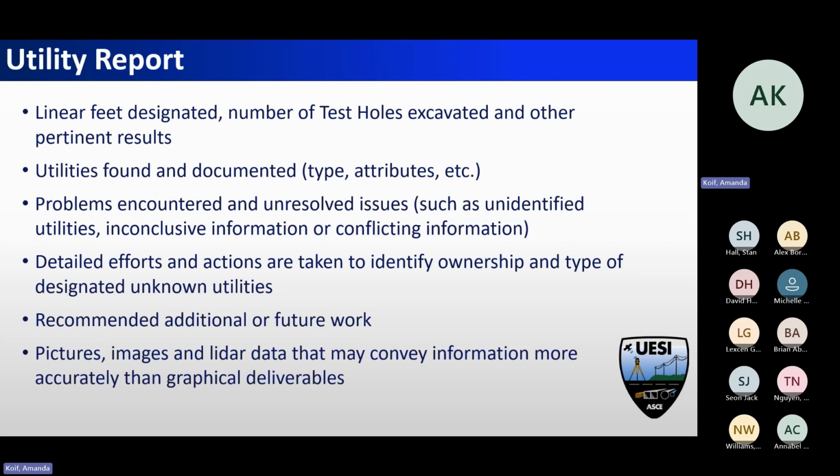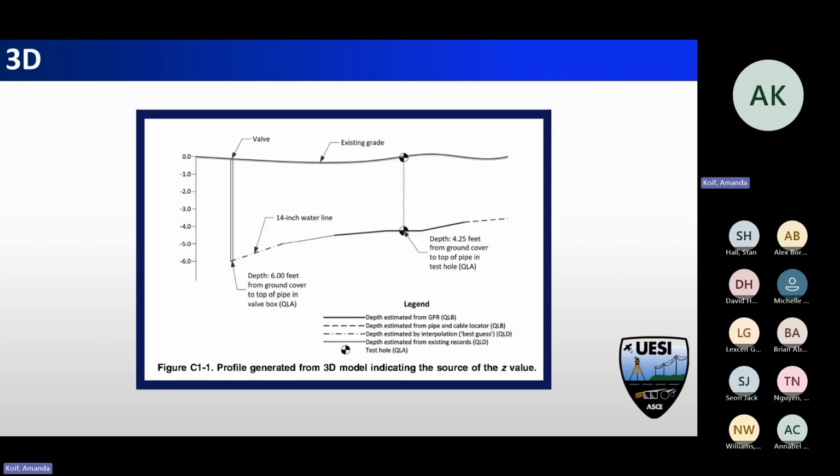And then all the pictures and LiDAR data and things like that, because a picture tells everything, especially inside those vaults. You can see what's in there pretty quick and have a general idea of, I have a big vault, but I may only have two lines in it, or if I have a smaller vault, but it's got 12 cables in it, then it'll help you determine how important those are, or how many issues you could have with doing those.